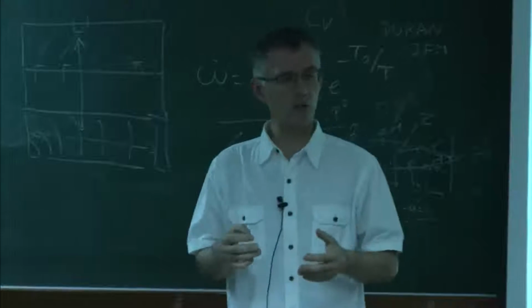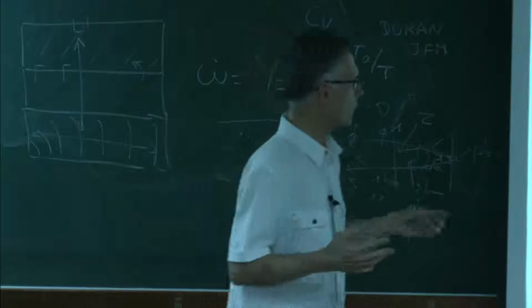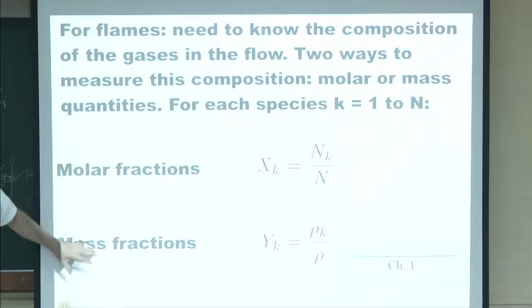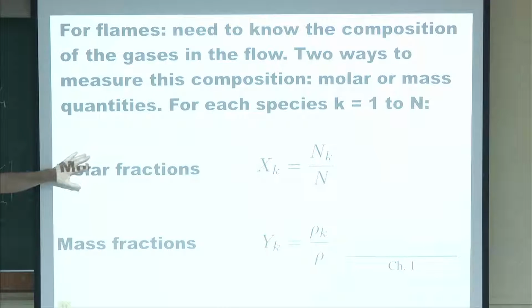Unfortunately, in our community, no one was able to agree whether we should work with mole fractions or mass fractions. For you, it's a pain because in certain codes, most 3D codes use mass fractions, but almost all the 1D and 0D codes work with mole fractions. So you have to know both, okay? But you have to be careful because, of course, everything molar and mass is not the same quantity. So every time you're talking about CP, for example, you have to know if it's a molar CP or mass CP because it's a big difference.